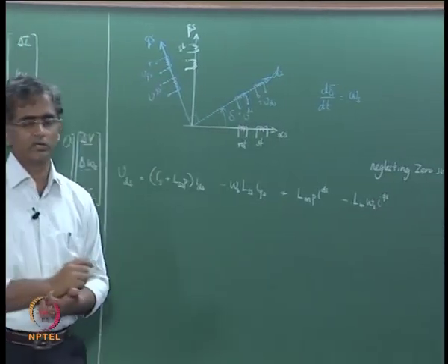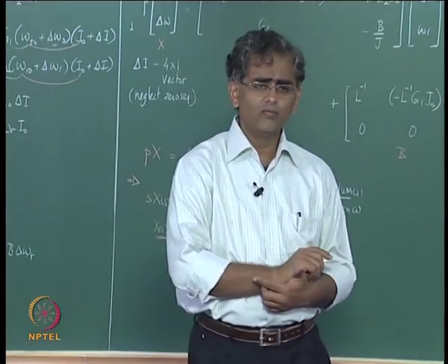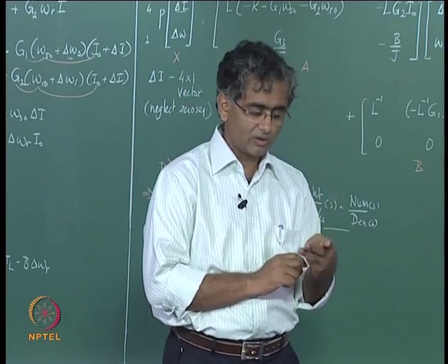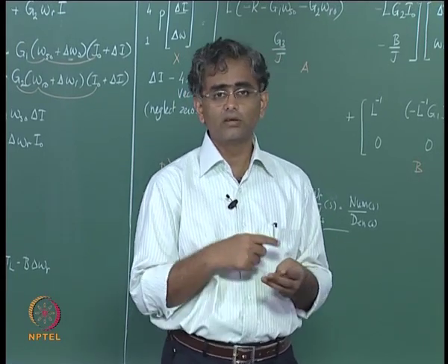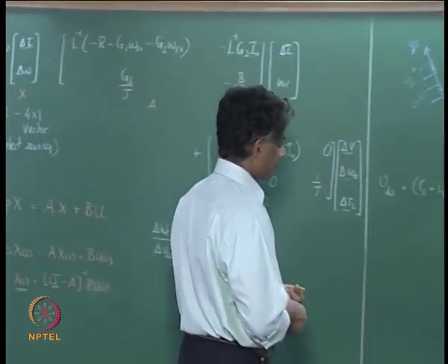Mostly that is true, zero sequence component does not flow in the case of an induction machine, because invariably the stator gets a 3 wire supply and zero sequence components are in phase, which means unless the neutral wire is there, there is no return path, and therefore zero sequence components cannot flow.